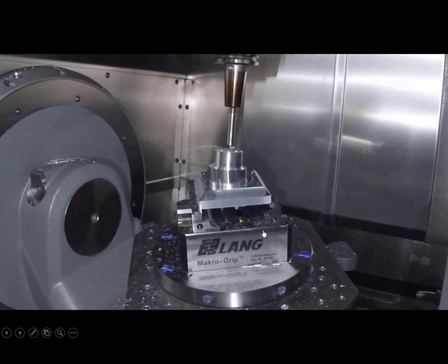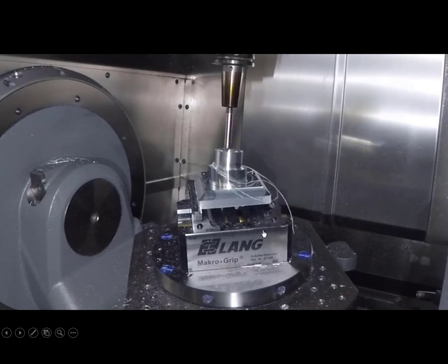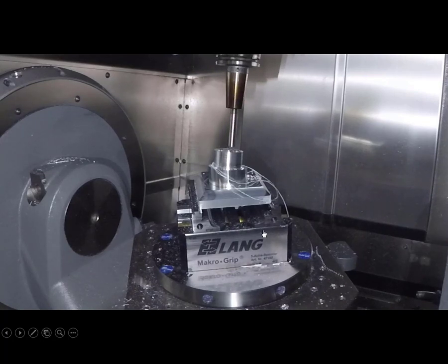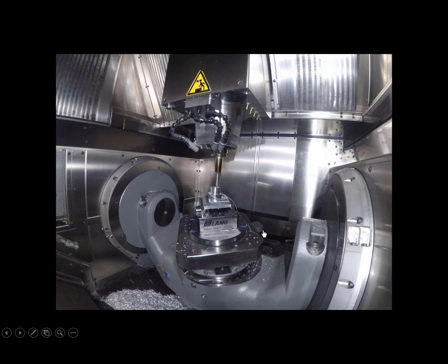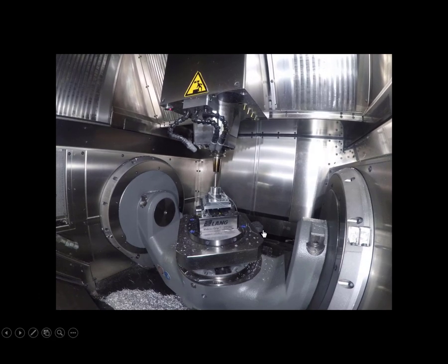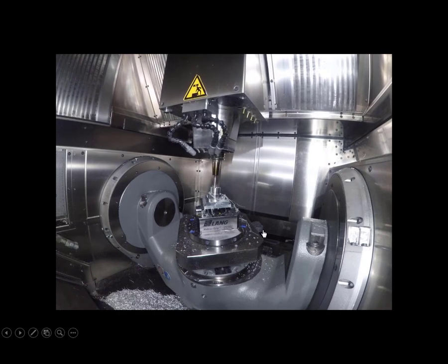So the best is always if you have a contour radius nearly the same as the tool radius, because then for an inside machining you can use nearly the complete spindle speed of the milling spindle to get a good cutting speed here. Of course, for an outside contour, the bigger the diameter is, the slower the cutting speed would be. It depends on the machine we are using here.